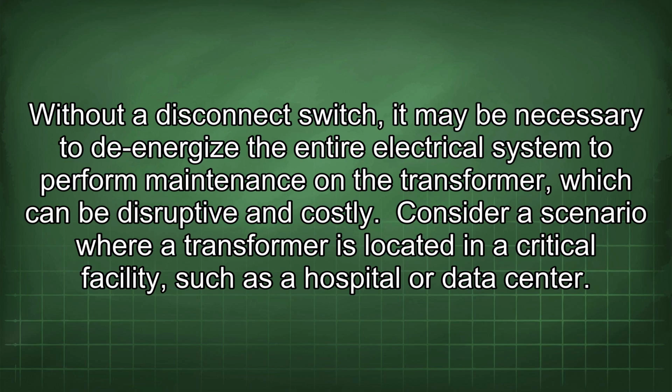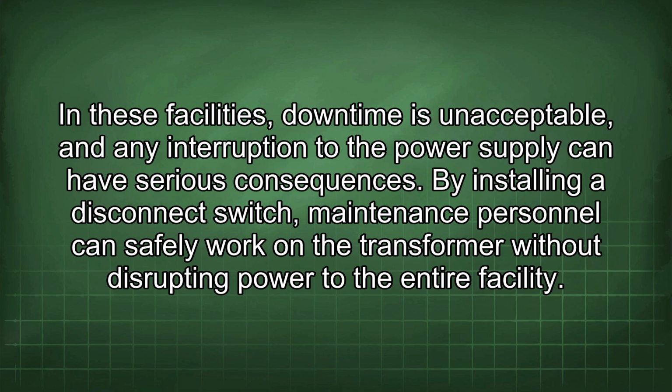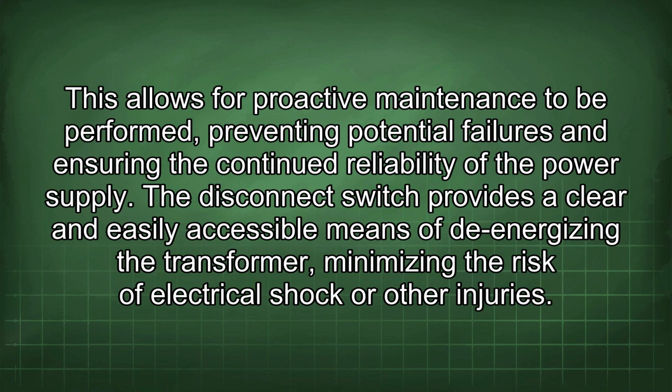Consider a scenario where a transformer is located in a critical facility such as a hospital or data center. In these facilities, downtime is unacceptable, and any interruption to the power supply can have serious consequences. By installing a disconnect switch, maintenance personnel can safely work on the transformer without disrupting power to the entire facility. This allows for proactive maintenance to be performed, preventing potential failures and ensuring the continued reliability of the power supply. The disconnect switch provides a clear and easily accessible means of de-energizing the transformer, minimizing the risk of electrical shock